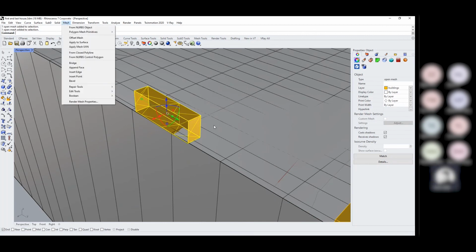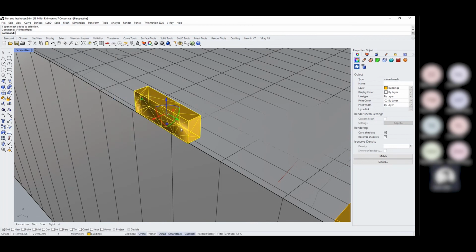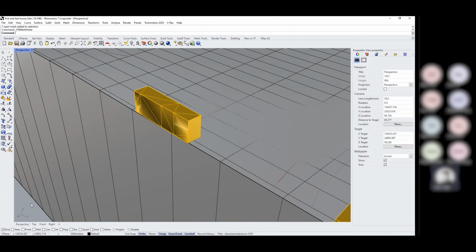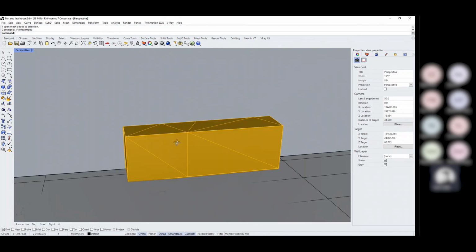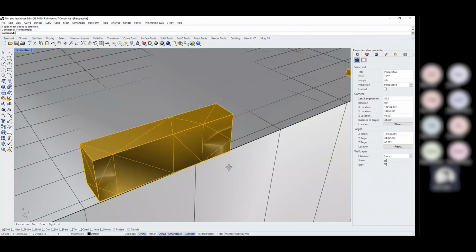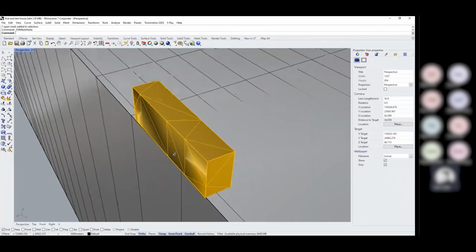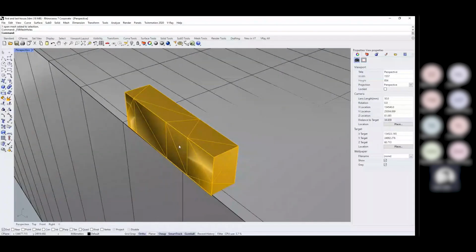And there's various things we can do with this. So for instance, I could select the object, go to mesh and mesh repair, fill all holes. And that's now made that a closed mesh. That in theory would 3D print. There's a slight problem with it, and I can see it by looking at it. All of these faces look correct, but when I look at the back, it's doing something weird. It's gone shiny. And this is a common issue called flipped normals.